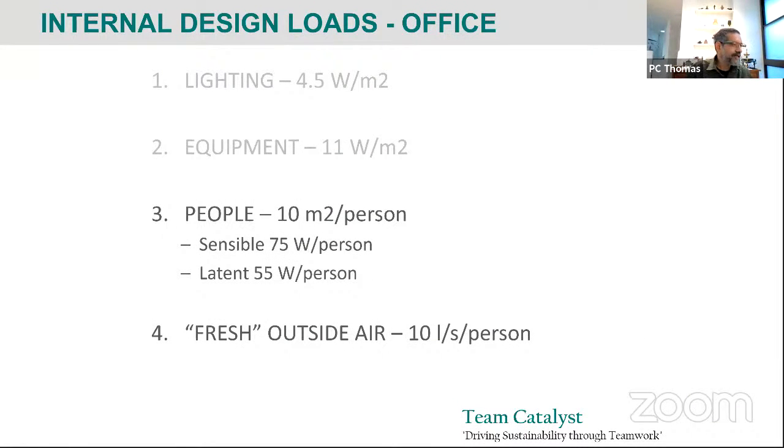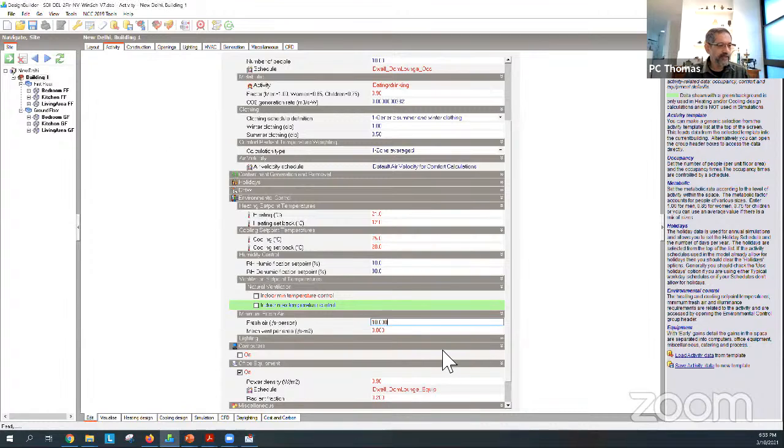So when you talk about the loads from people, you have the heat that is generated by the people, but you have to bring in outside air so that the oxygen levels, CO2 levels, all that stuff is taken care of. When you bring in that air with a ventilation fan, that brings both temperature and humidity into the space, and the air conditioning system needs to deal with that. That's why you need to provide that input to the model, which is what you're doing here. Now, there are two ways of providing input.